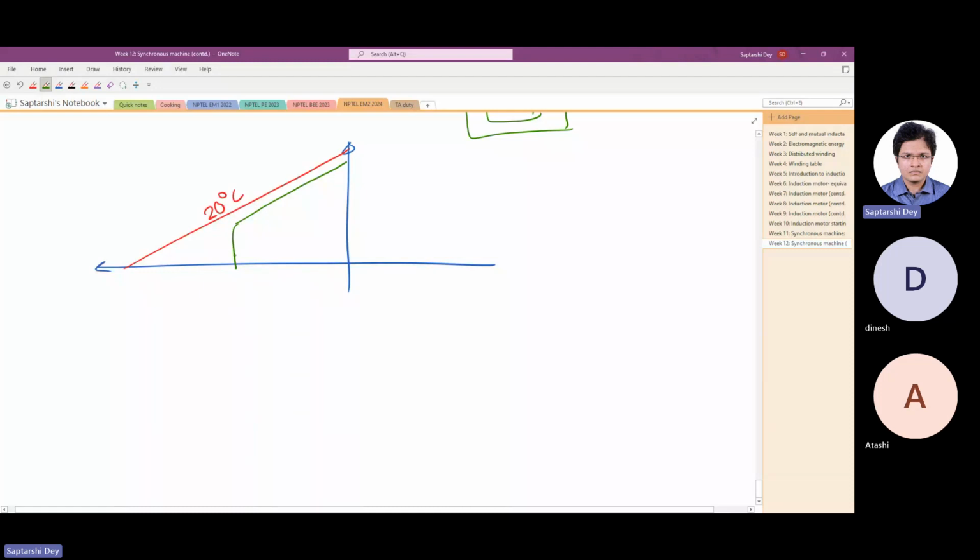So there is a good possibility of demagnetization at 100 degrees centigrade. So you have to make sure while designing the machine that even at full load or full field weakening, you are not crossing this knee. You must not cross this knee. Your magnet will be completely demagnetized. You have to remagnetize it again.